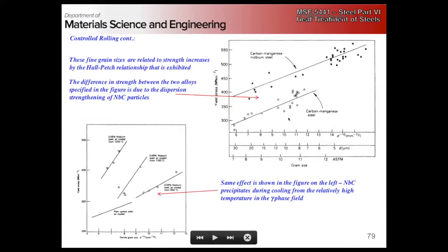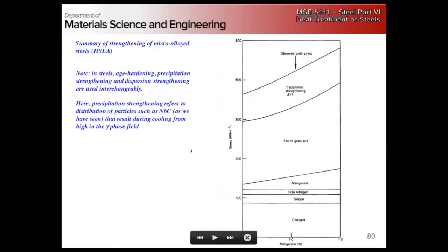Of course, there's nothing new here. This is essentially Hall-Petch effects and dispersion strengthening of the secondary phase carbides, which are also our pinning, grain boundary refining elements.